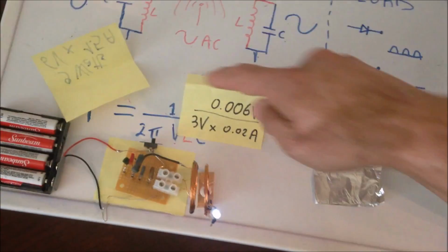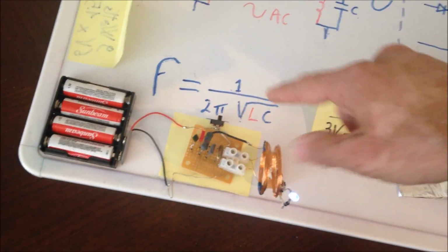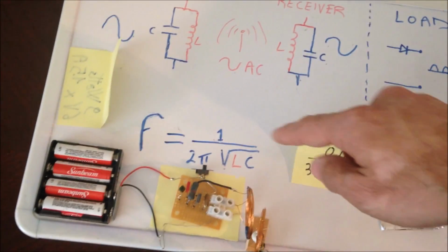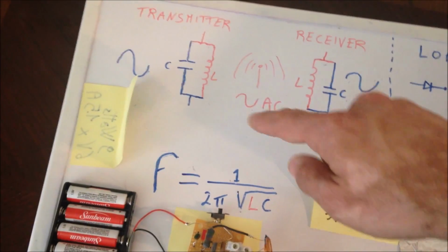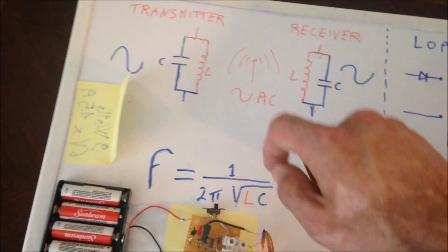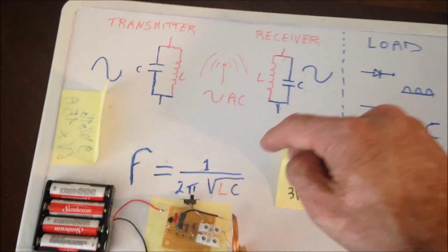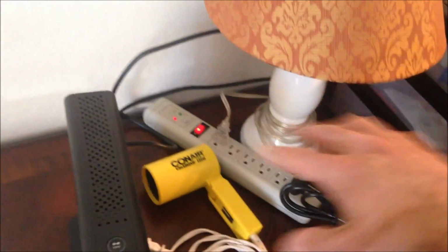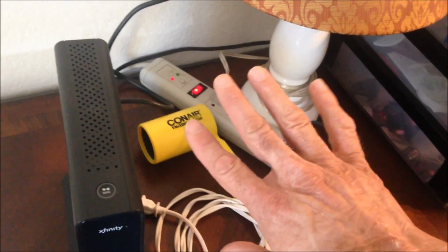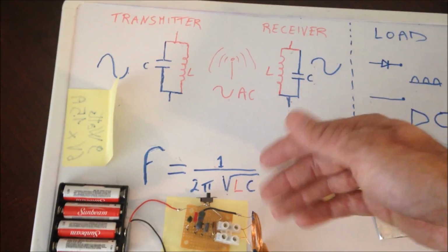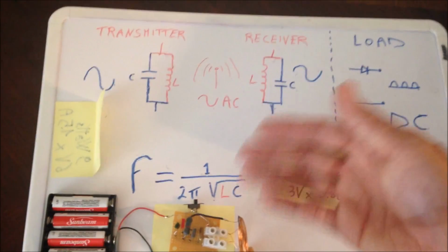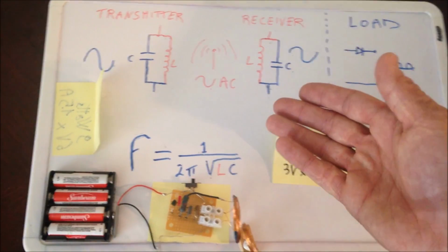Now, if we're going to do a little bit of math, in order to listen or to tune your receiver to 50 to 60 hertz of frequency, that will require an antenna just as long as 1,000 miles. Yes, 1,000 miles to listen to your household equipment right here. 50 to 60 hertz. According to our math here, we need an antenna approximately 1,000 miles long. That's totally insane and totally useless to do.